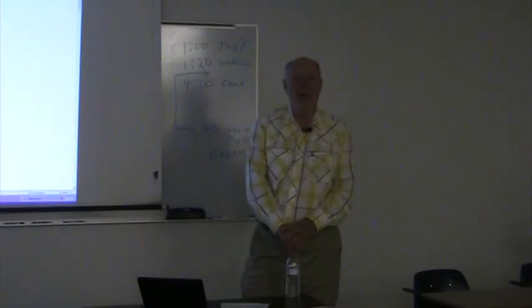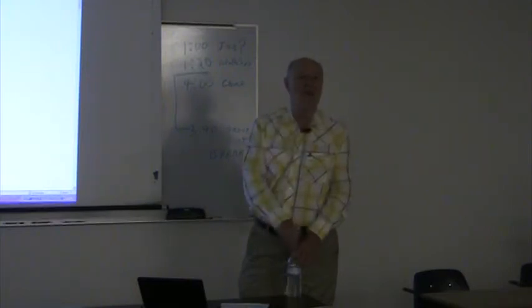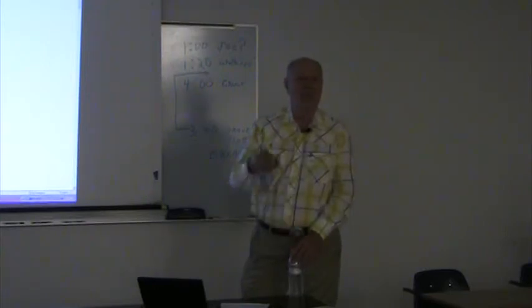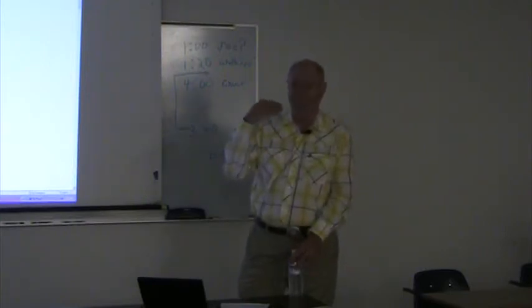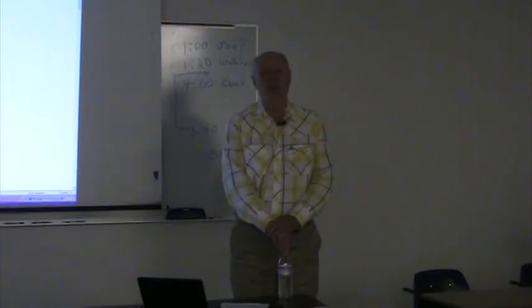It is literally magical that our chips don't require very much power. Bill, you're talking about 20 milliamps for the PIC, and we are 7 milliamps for one of our nodes running flat out. Asleep, we are 1,000 times smaller. We are an ancient technology. 0.18 micron isn't interesting to anyone except us. We like it because it's relatively cheap.